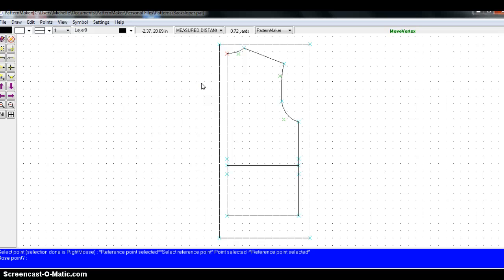Turn on Snap to End Point. That is Control and F3, holding those at the same time. It is a quick one to put us into the Snap to End Point. Now select the same point you're moving. Make sure the X appears indicating that you have a snap point. See how it jumps around to snap to points on the endpoints.